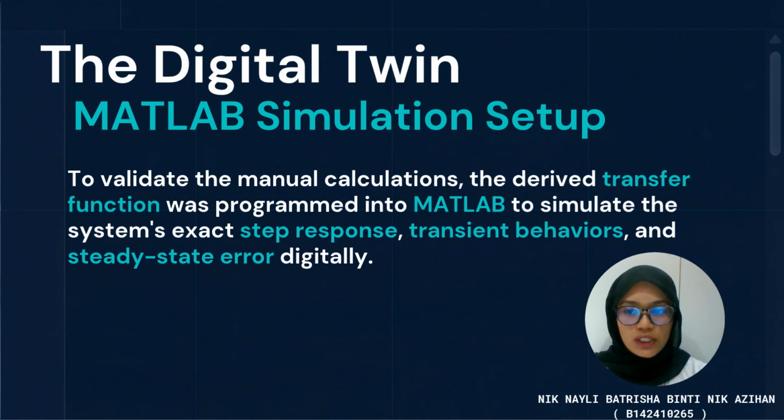Moving to the next slide, which is about the digital twin MATLAB simulation setup. After obtaining the theoretical results, we validated our transfer function using MATLAB simulation. The transfer function was programmed into MATLAB to simulate the system step response, transient behavior, and steady-state error. This digital simulation allows us to compare the theoretical calculation with the actual simulated results and verify that our mathematical model is accurate.